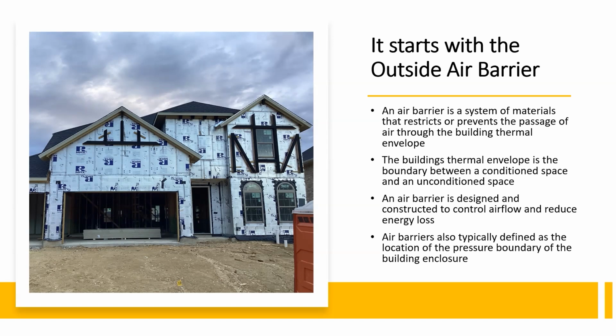So lastly, with a single family, the air barrier system also includes the separation from garage and the conditioned space. A lot of framers and insulators look at that as just an interior wall. It's not really an interior wall. It is, because it meets the interior side, but it's not an exterior wall. So they don't treat it as such, but it must be treated as such. It can also be defined as a gas barrier, providing a gas tight separation, or contamination barrier, between garage and the rest of the house.